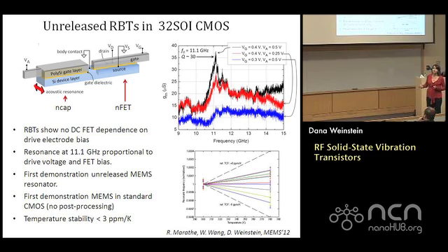Also, we wanted to get rid of these spurious modes, and a large feed-through, which actually happened due to capacitive feed-through through the silicon and directly from drive to gate. So these are things that we wanted to improve on for the second run. But one thing we got for free out of this process was passive temperature compensation.